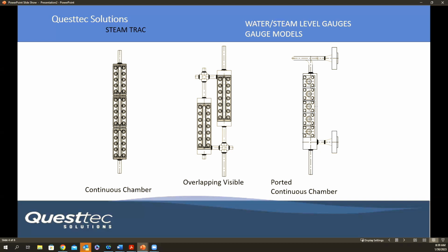There are red and green lights, and because of the trapezoid shape of the chamber, the refraction angles of the light change. So when water fills the chamber, instead of red shining through, green begins to shine through. I just want to get everyone on the same page on the different varieties of direct reading sight glass, and we will continue on to designate what PG 60 and ASME Section 1 tells us is required.